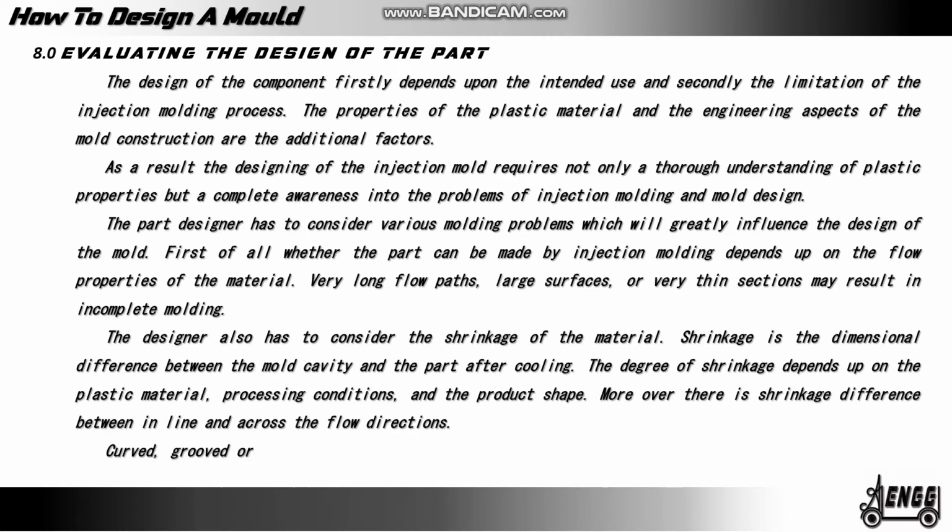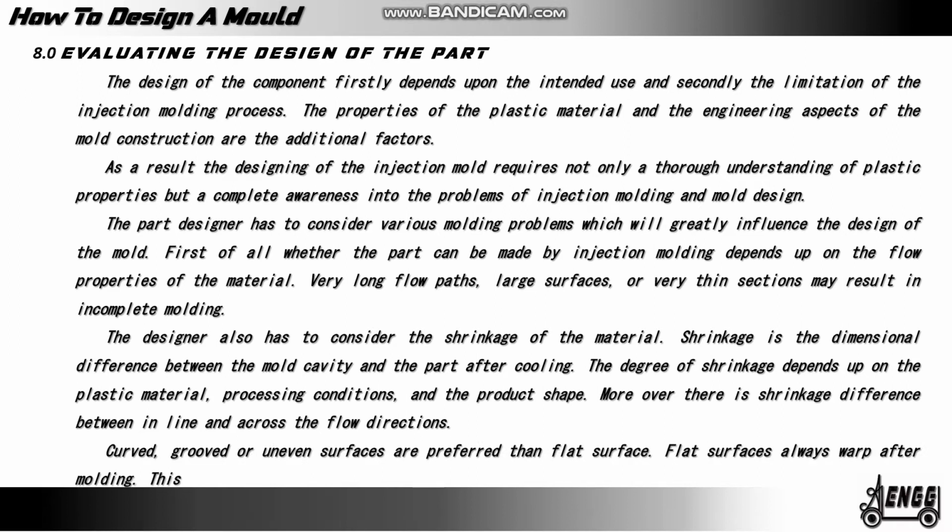Curved, grooved or uneven surfaces are preferred to flat surfaces. Flat surfaces always warp after molding. This warping can be prevented by providing ribs, but ribs can cause seam marks. All the corners should be rounded to prevent the chance of cracking and also to increase flow.